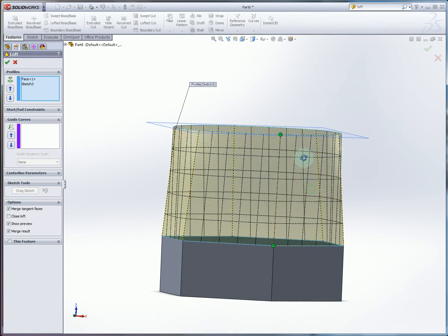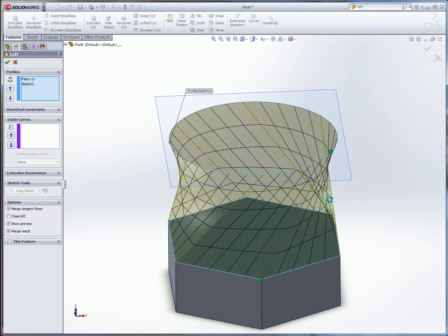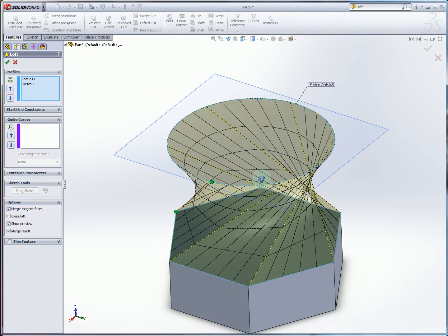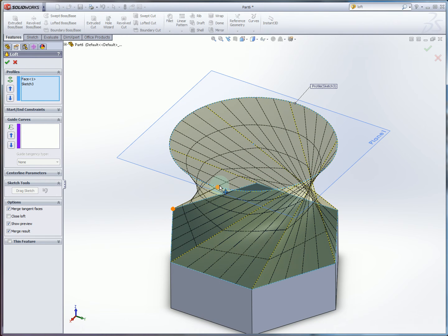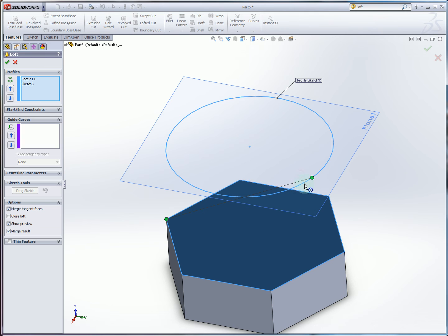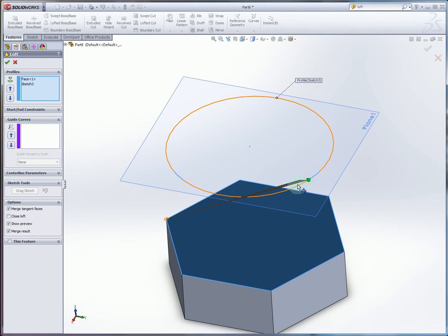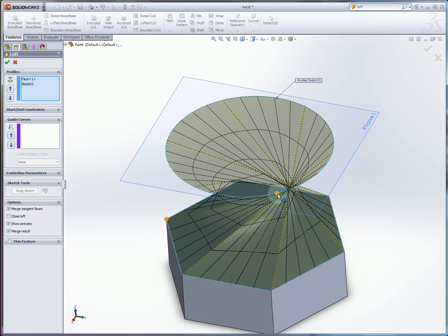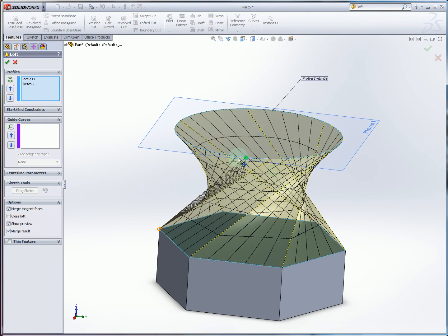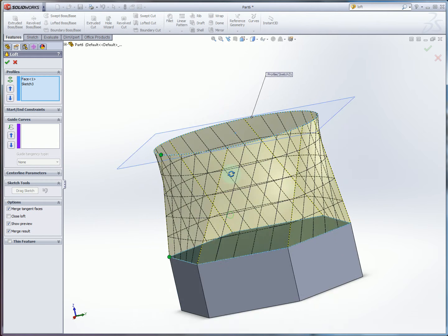So by having the connecting line straight out, you get this straightforward blend, but you can also get this kind of crazy twisting, almost an iris effect, just by dragging the connecting point around. Now, you can, of course, take it too far. If the section self-intersects, it won't solve, as you can see. But for the most part, you can create a pretty impressive variety of shapes just from this very basic specification.